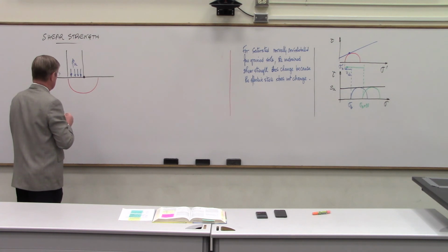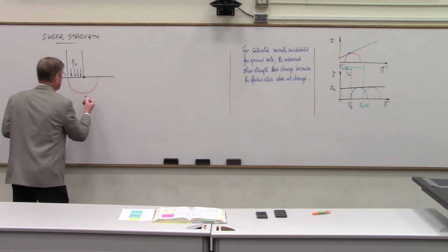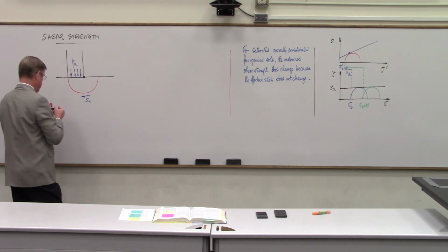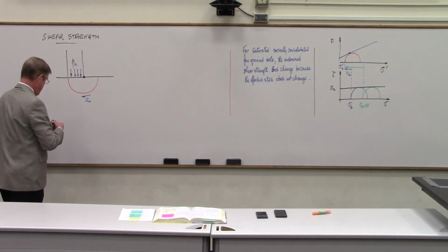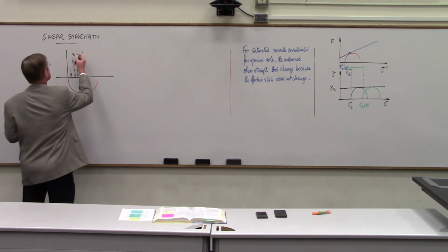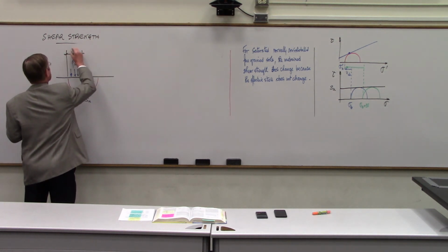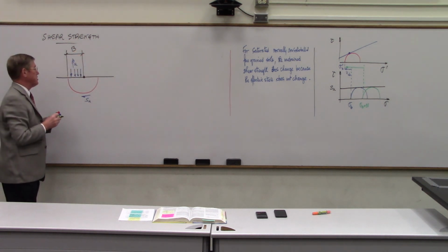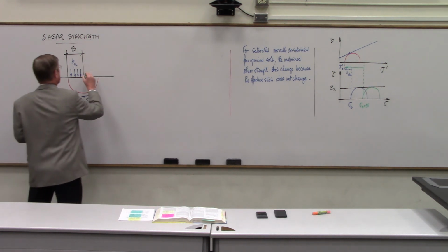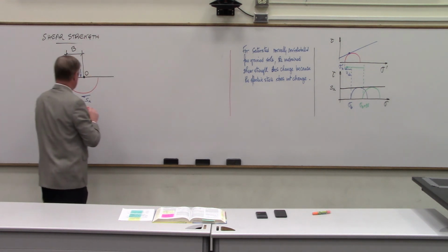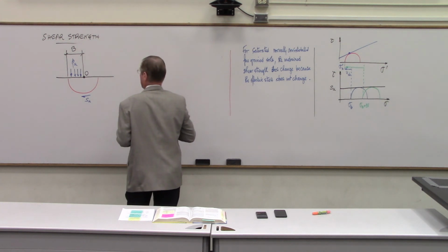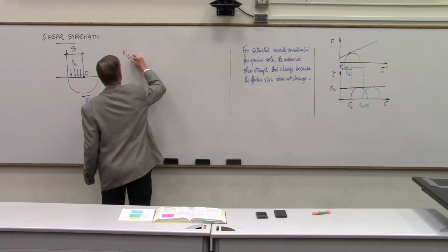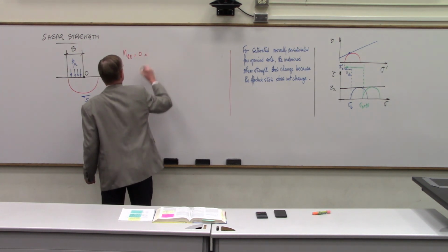And along this circle, we're going to have the undrained shear strength, S sub U. The width of the tower is B, and I'm simplifying by taking a plane strain condition, and I'm going to write moment equilibrium around O. So I'm writing moment around O equals 0.